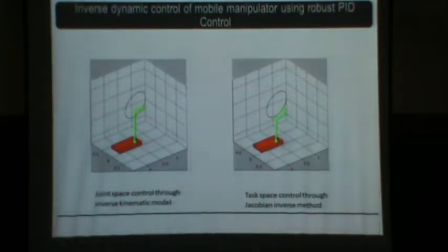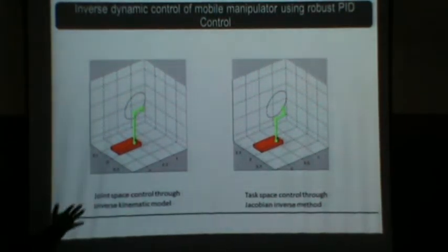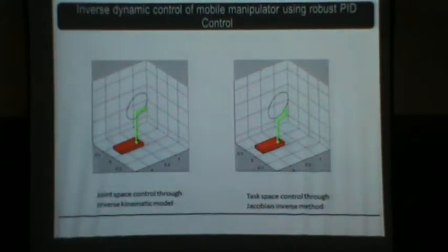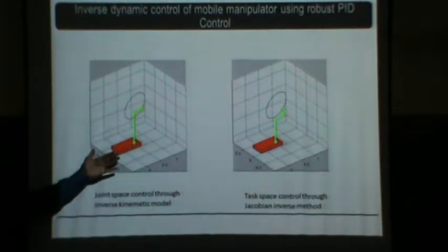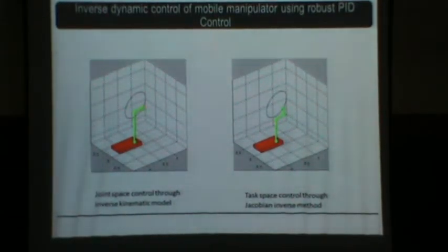And one another thing we want to compare. We are saying that everything we are trying to control in task space for the mobile manipulator is kinematically related. But why can't I do some optimization, and try to get the inverse kinematics through optimization? Probably I can apply a numerical method. Here you can see that there are 5 unknowns, correct? And 3 known. So you can start estimating with the numerical method. You start with some approximation and you try to get it to converge.